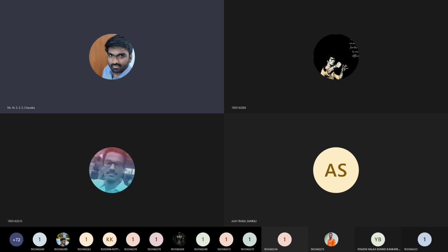And then you have ECN minus EF equal to half EG minus E2. So let us call this equation 1, this equation 2 for the time being. If we add 1 plus 2, we'll get EF minus EVP plus ECN minus EF equal to half EG plus half EG, which is EG, the energy gap, minus of E1 plus E2.